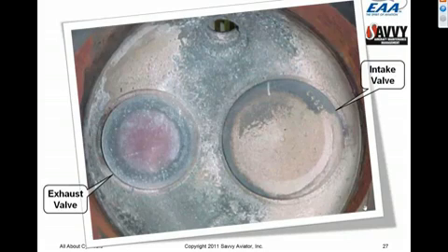And the fact that it's symmetrical tells us that this valve is running at equal temperature all the way around the circumference of the valve, which means that it's sealing properly and doesn't have any leakage or heat sinking problems. So this is a real good-looking valve. You can also tell that this particular engine has been run very, very lean, because the amount of deposits on the valve is very, very small. So this engine undoubtedly has operated lean of peak most of the time, and this is what we like to see: a nice clean cylinder head, nice clean valve.